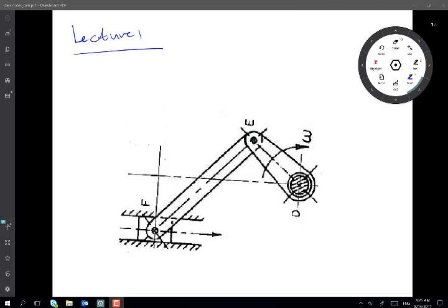And the crux of machine design is really a linkage, and that's the part of the machine which receives power or motion from a prime mover, be it an engine, an electric motor, or a hydraulic cylinder, and then transforms this energy to the other end of the machine in a specific, mathematically based fashion to move some other part of the machine in a calculated way.